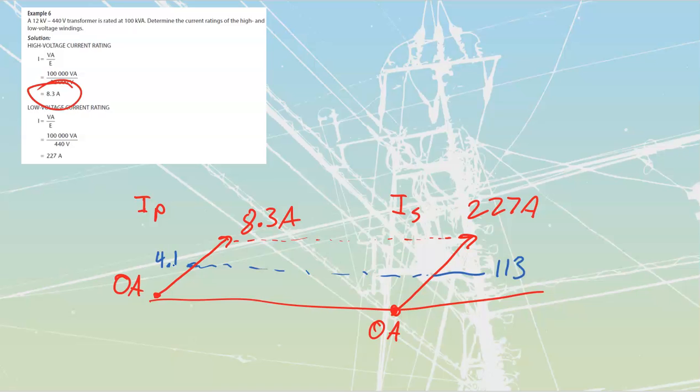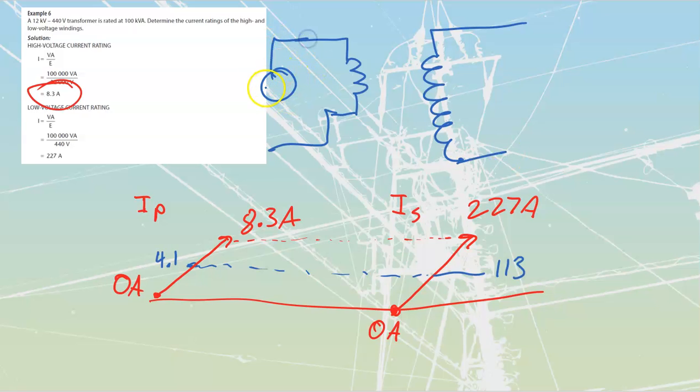It's super important to understand that it also operates on both the high voltage side as well as on the low voltage side. In other words, if I could take a transformer and feed out a low voltage, I could also take the same transformer, reverse it, and feed in with a low value of voltage, and get out a high value of voltage, right? Now I can make my source, this side over here, the 440, and I could get 12 kV out on this side, and that 12 kV I could place across some resistance over there. I'm still going to follow the same thing. I'm just going to interchange their values, right?